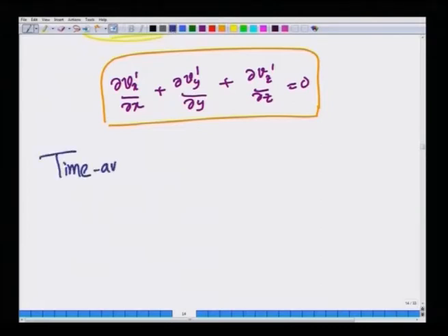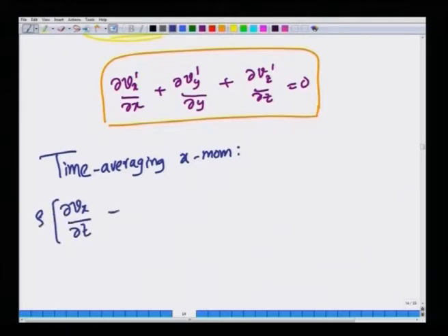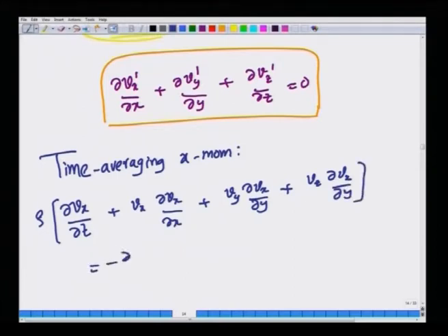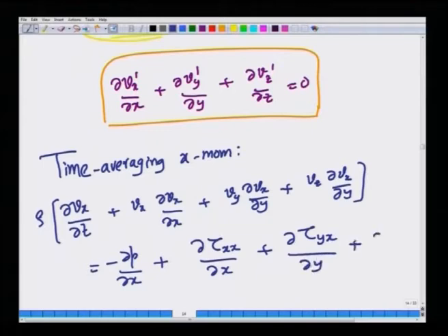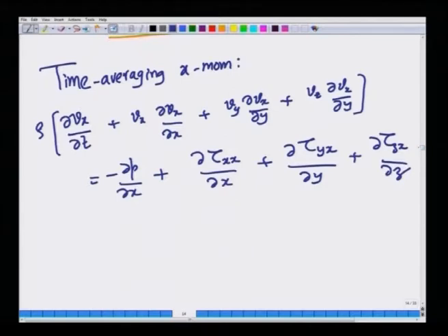I am going to specifically take the x momentum balance. First, write the entire x momentum balance in Cartesian coordinates in the x direction. Plus you have, now I am going to write my expressions in terms of only the stresses, and the reason for this will become clear a little later. I am not going to use the Newtonian constitutive law. I am going to write this as the Navier-Stokes equation before substituting the constitutive relation for the stresses. This is what we call the Cauchy momentum equation.